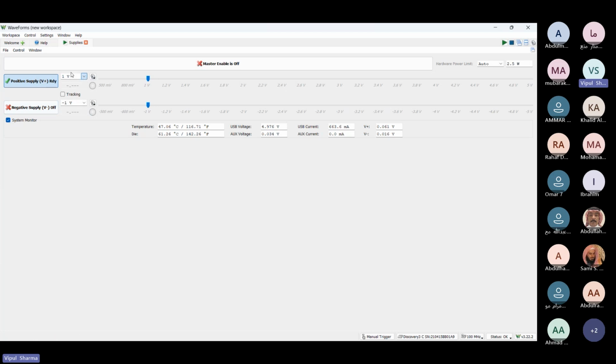As you can see, there are no voltages available more than 5 volt here. So the maximum supply which can be provided, or the signal which can be measured, can only be 5 volt from this measurement device. Just apply the supply voltage. We will not enable it before we make all the settings. Once all the settings are done, only then will we enable the power supply.